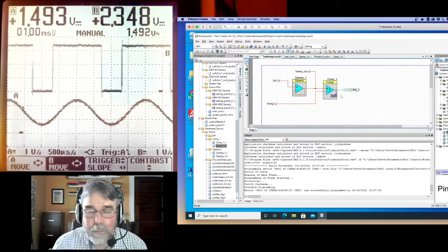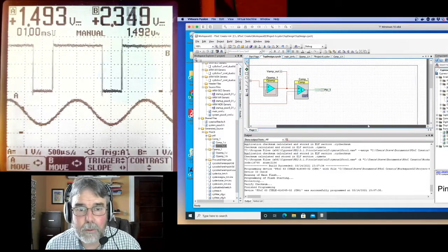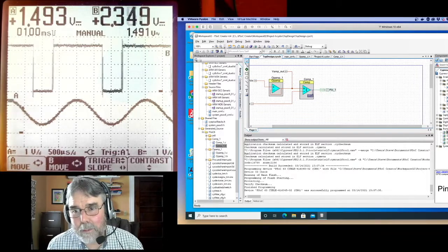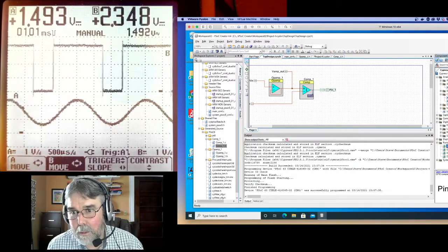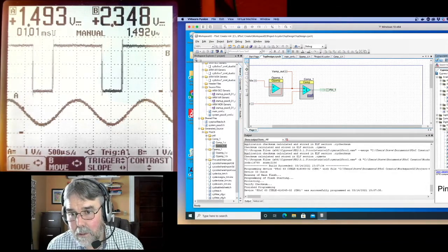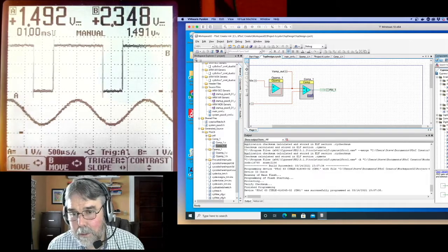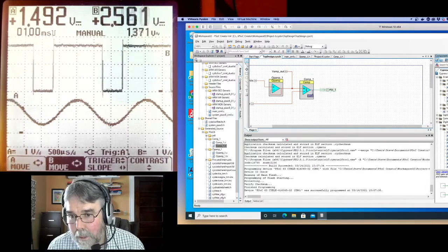Now let's add a couple of those flip-flops. I'm not going to add every single flip-flop. You can add the other three, and also the AND gate. I just want to show you how it's done. The AND gate is here, I'll let you get that. If you click on it, you can see the image. Basically, it takes 2 bits in, and it puts out a bit that's high if both of the input bits are high. So it takes 2 logical inputs and produces 1 logical output.